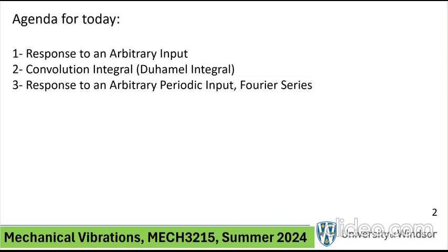This omega on the right-hand side is what was called the driving frequency of the force. And this type of loading actually is very common. For example, whenever you have rotating machinery, fans, propellers, compressors, etc., because of the general unbalance in the rotating component, there is always a harmonic force applied. In the case of, for example, a single degree of freedom system, you can imagine that there is a motor that's turning, sitting on a mass, and it's exerting that unbalanced force in the form that I mentioned to you. We spent 3 weeks solving that and coming up with all kinds of scenarios and all kinds of graphs, etc.